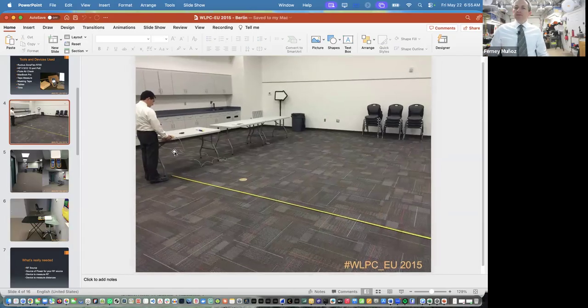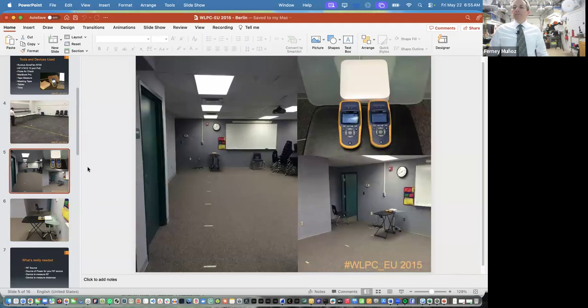So I placed the access point and then started measuring at different distances, and then it happened that every time I moved, like when I was measuring, it changed. And I said, there is something wrong with this measuring device, because it was like negative 55, negative 53, negative 58, negative 55, and it was changing all the time.